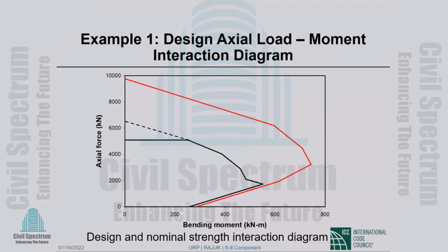What I suggest is, as I suggested the other day, you draw the joint to scale at the design office, and if you find that bars don't fit, or after you put the bars in, concrete doesn't go in, then change something in the design. You cannot just bend bars, or set bars aside, or drop bars.